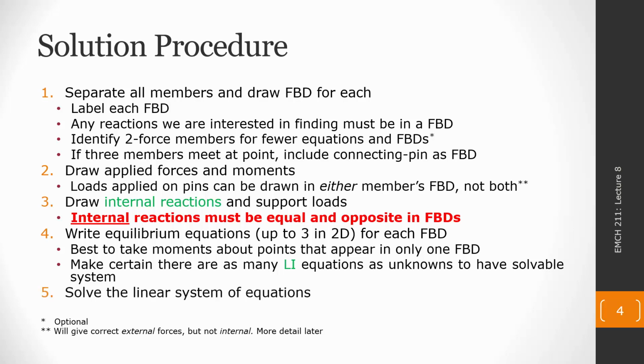The order we write our equations in, the order we draw our free body diagrams, and the order we solve doesn't matter in the end as long as we have a solvable system of equations. But we're going to see that, again, when solving these by hand, there are some strategies that just make solving steps a little bit easier when we are trying to do this manually.